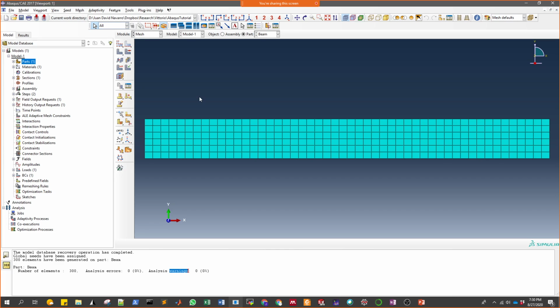Well, regarding structured meshes, the thing is you don't have much flexibility on using a structured mesh. And a structured mesh is for a very simple geometry like the one that I'm modeling. But for example, if you have a complex domain and you want to use an unstructured mesh, my suggestions are: try to add partitions, and then you can fit small elements in these small areas. That will help the mesh a lot.